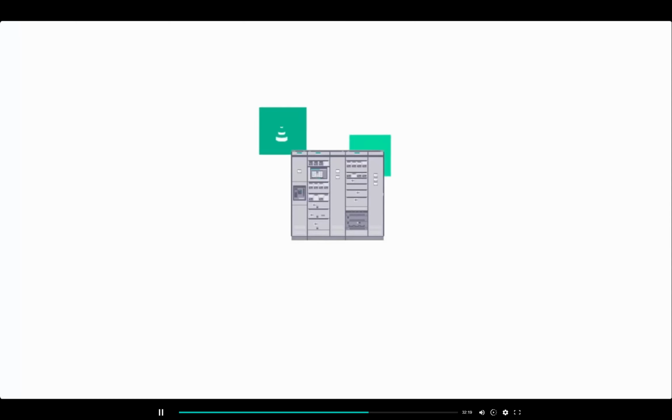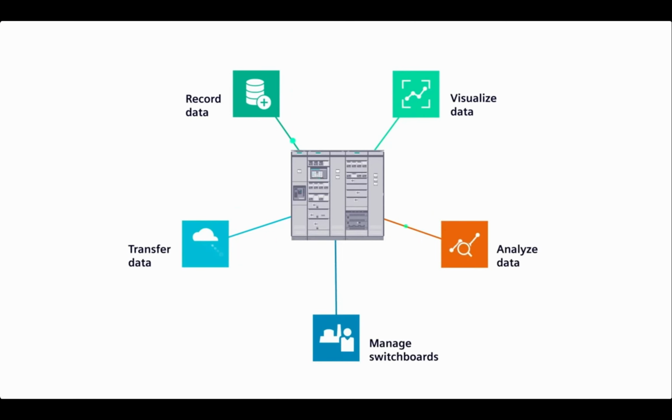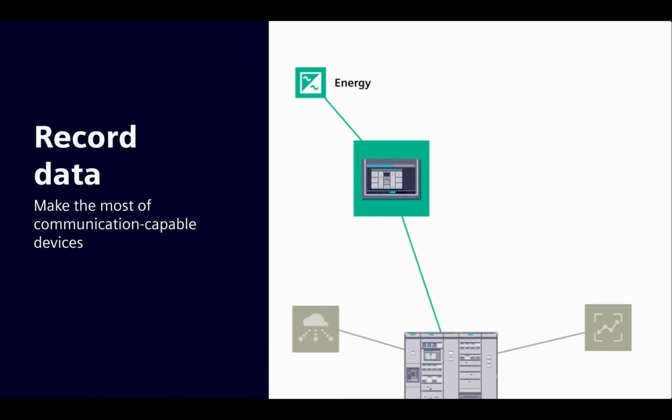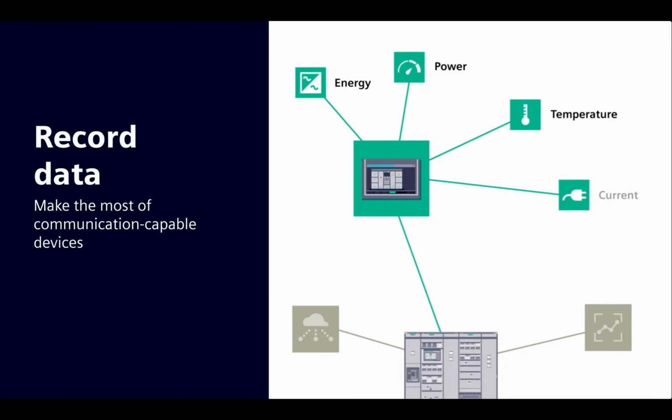Device data from the previously mentioned components is collected and recorded using the available communication protocols such as Profinet, OPC UA, or Modbus. You must add a certain security margin so that you don't get this problem. The other thing you also have to take into account is, you have to look into the future, because you calculate your setting. When you install the device, communication is established but you don't want to reconsider the setting every month. That means you must have a primary setting which is also valid after some years, when maybe the process control system is not interfered with.